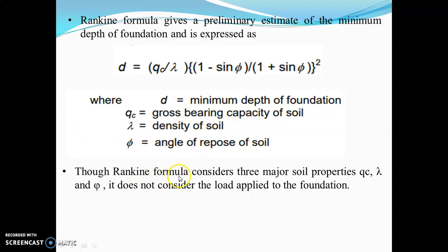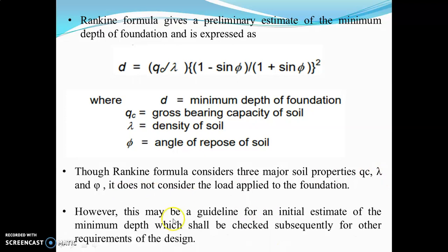Though Rankine formula considers three major soil properties, QC, gamma and phi, it does not consider the load applied to the foundation. However, this may be a guideline for an initial estimate of the minimum depth, which shall be checked subsequently for other requirements of the design.